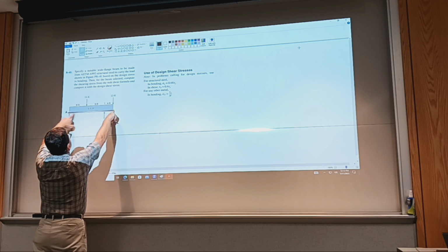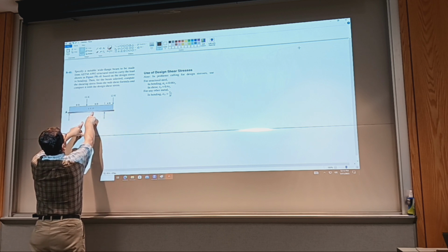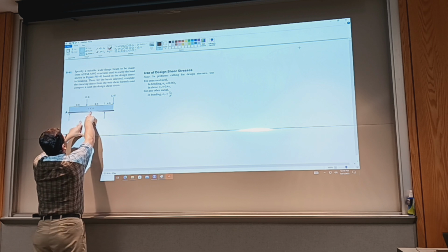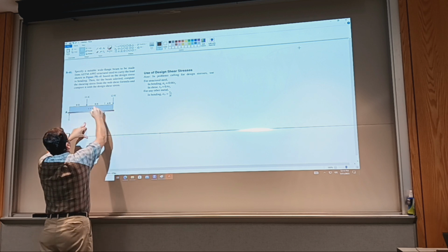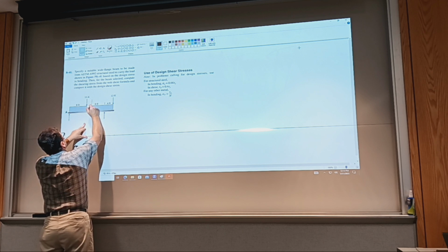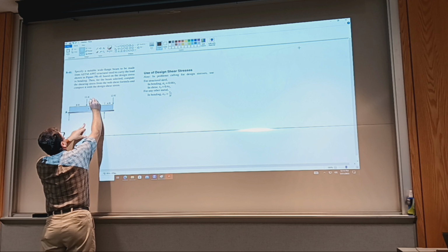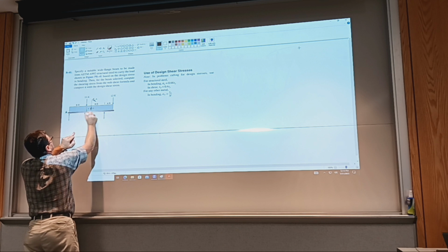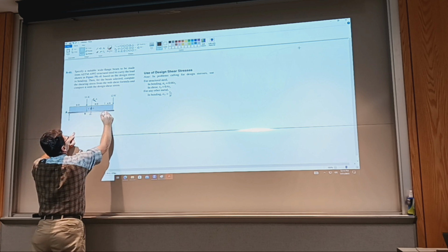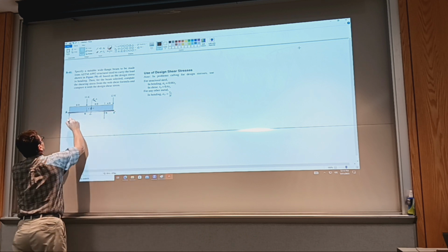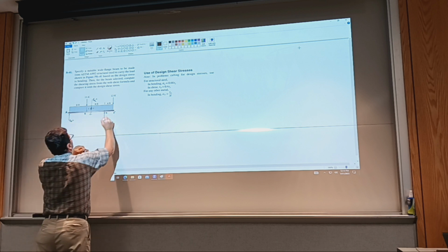This distributed load has the equivalent concentrated load at 10 feet, that is in the middle. So just for that I'm going to introduce a notation. So this is F equivalent for the distributed load. So I have A, and then there's point B. I have C here, there's D, and then there's E. Okay, so we need to evaluate RA and RD.